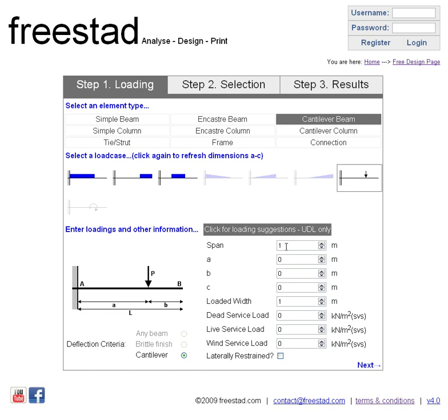We simply need to enter now some loads and some dimensions. Let's say that the beam is 3 meters long, and let's input our dimension A as 2 meters. And let's say that the beam exists every 2 meters, so it's got a loaded width of 2 meters. And then we enter in some standard loads.